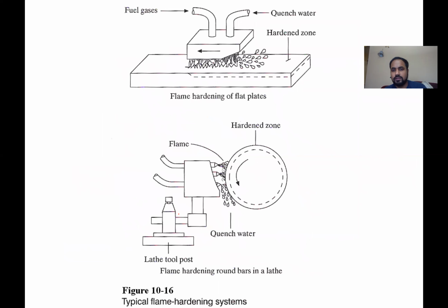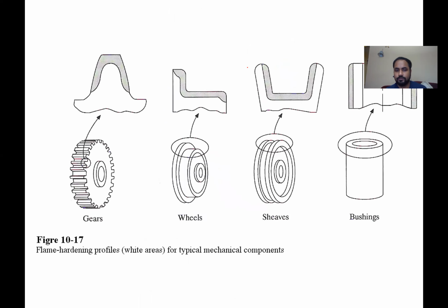Okay. If you want to make part of the material stronger, you can do a localized heat treatment. For localized heat treatment, you can do flame hardening. That means you heat the material in a small region and then you quench that, then move ahead and quench it. You just don't do it on the whole material. That will give you a localized hardening, which sometimes is desired, sometimes it's not desired. So if you want some localized strength in a particular region, you can do flame hardening, right?